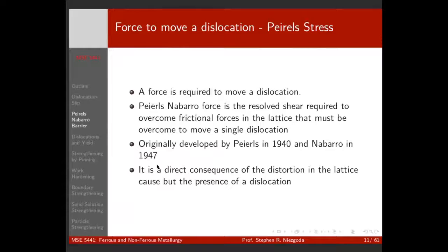Then you could take them out and do etching and look at how the dislocations had moved under a given load and calculate dislocation velocities that way, before the electron microscope was ever built. So before we think about how to get things in the way of dislocations, we have to think about how hard it is for a dislocation to move in the first place, right?